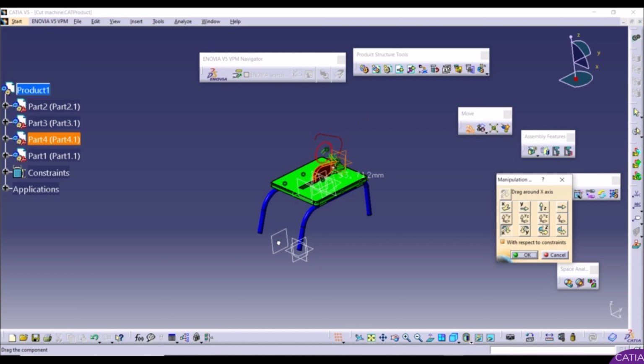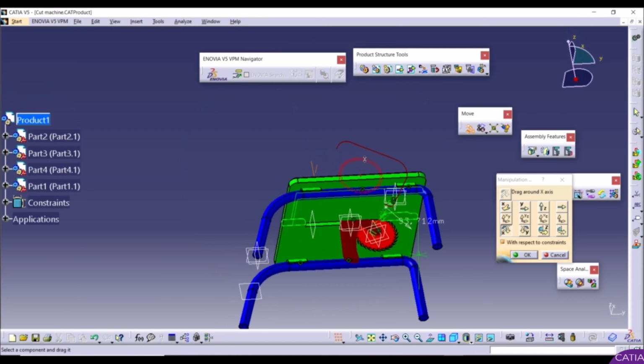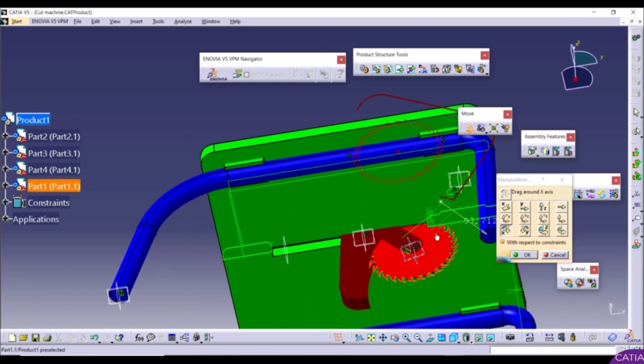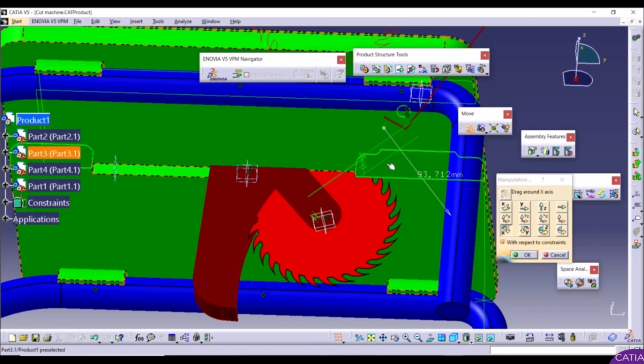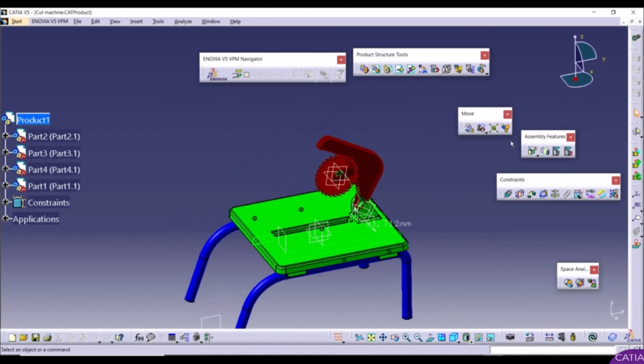And now you can see that here we have collision. But our software doesn't recognize this collision, as you can see here. Here we can see that one part interferes with another part. If you want to simulate the reality here, we have here option, stop, manipulate on clash. So let's go back, like this. Let's check here, stop, manipulate on clash.